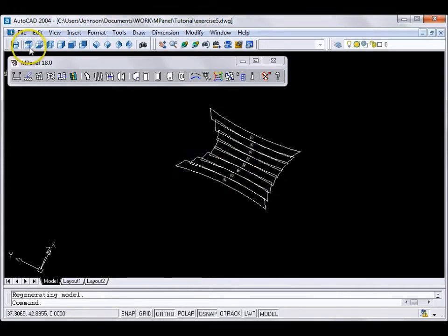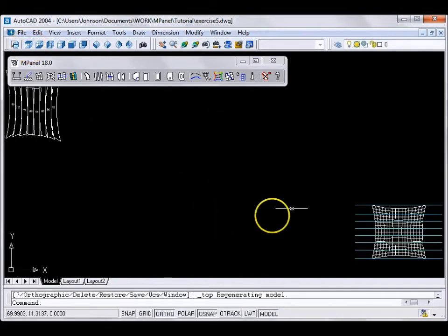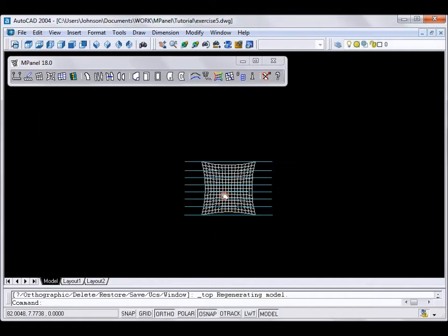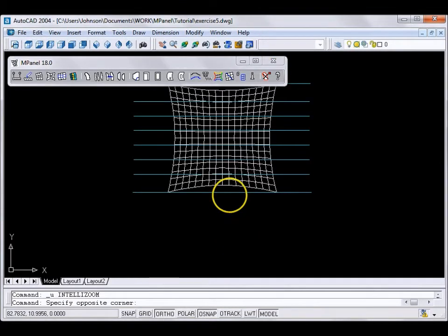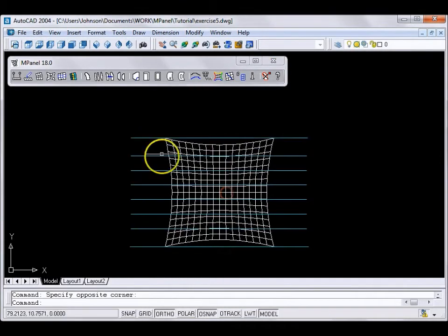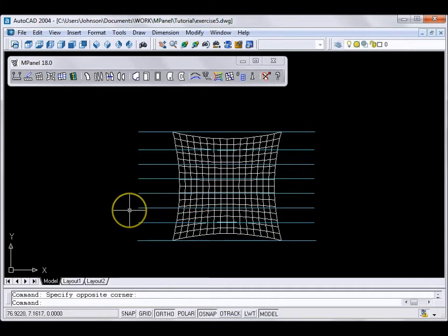In order to demonstrate how to do this, I'm going to switch over to a copy of our original hyperpar, and as you can see, I've drawn 8 horizontal lines across the mesh, 6 in the middle, and then 2 across the ends. These blue lines show where we want our cross-sections to be, and can of course be drawn differently to get different sized cross-sections. What we'll do is run the cross-section tool, which is going to convert these lines into 3D polylines inserted into the mesh, creating 7 cross-sections.